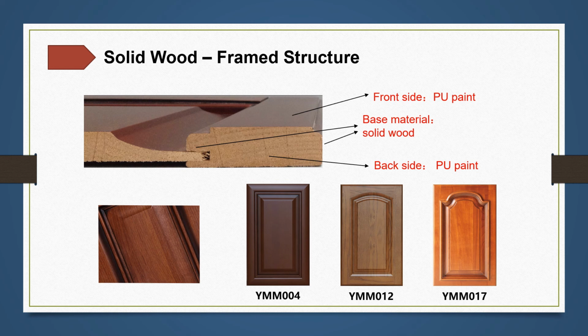Okay, so the first part is the available dimensions of a door panel. The dimension of a big board is 1220 by 2440. In consideration of avoiding possible deformations, loss in panel cuttings, and edge sealing problems, we set the following limitations. Take a look at the sheet here.